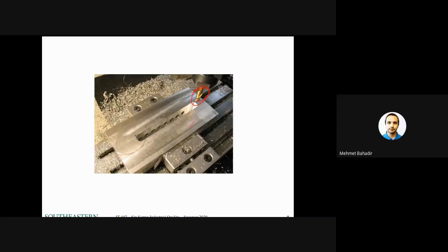Also, if we concentrate on the material that we are cutting, the type of the material, right? And the setup that is holding it, and the machine spindle speed, feed rate, and if you're using a cutting fluid or not, chip removal systems, those are all parameters that can contribute to the changes in the system, and that they can cause significant variations in the final product, which are assignable causes.